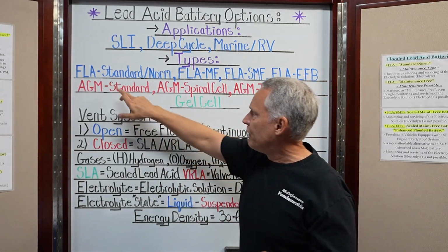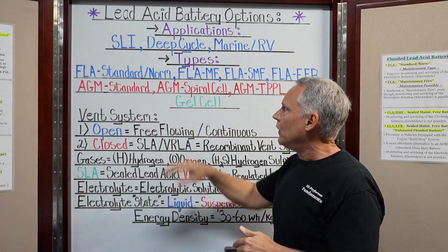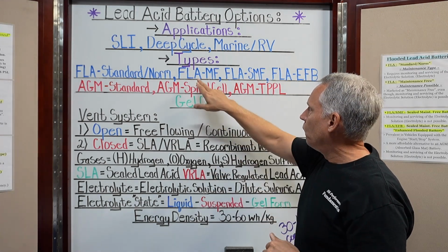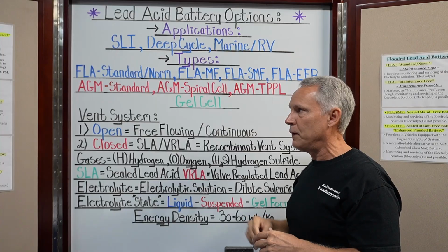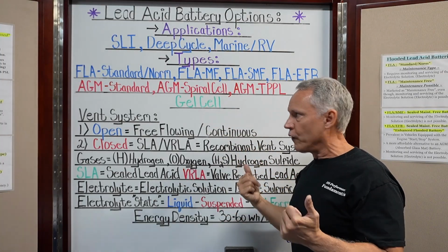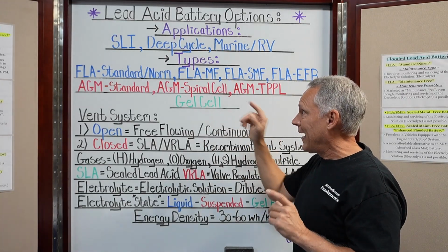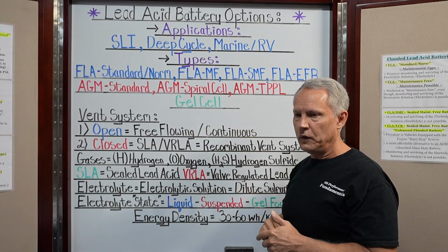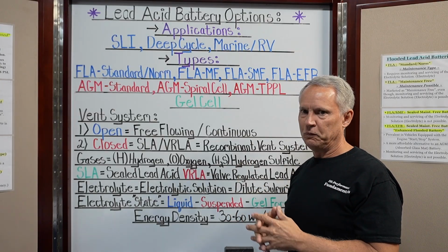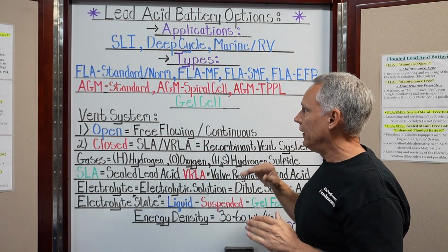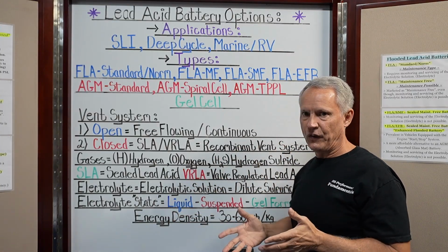So, if you have a flooded lead acid battery that's a normal electrolytic solution or a liquid electrolyte, you do need to maintain it. And here is what I call an advertised maintenance-free battery. They say it's maintenance-free, but it still has removable caps. You can still service it the same as you can the standard norm battery. It's really just advertising or marketing. And if you can maintenance the electrolyte, you need to. If you can see it and you can address it, you need to be doing that, or your technician needs to be doing it. Somebody needs to be doing it, okay? It just needs to be considered normal maintenance. It's not a bad thing. It's just a maintenance thing, right?